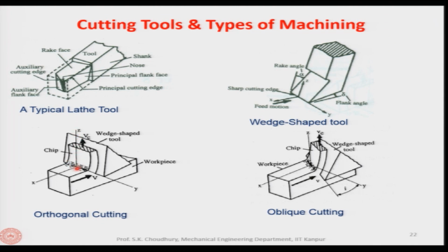And the forces imparted to the workpiece will be confined to the x and z plane only, because the tool edge is perpendicular to the cutting velocity vector. There will be no side spread of the chip, and the chip will flow exactly perpendicular to the cutting edge.